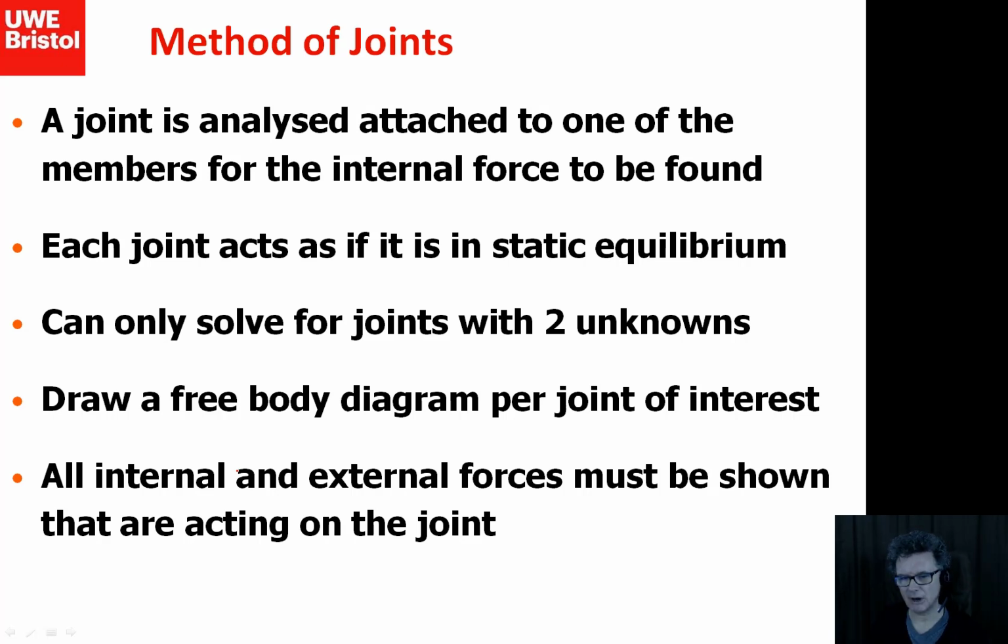Each time we are at a joint, we're going to draw a free body diagram of interest, and we're going to show all the internal forces and all the external forces acting on that joint. And it's a good practice to first draw your first free body diagram, just showing algebraic representations of those forces.